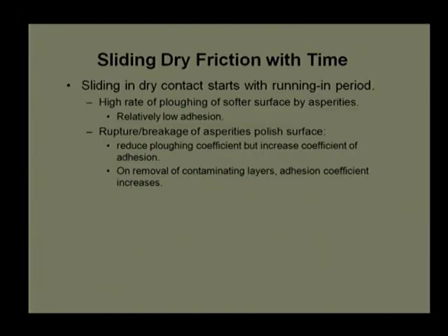And there is an observation which we got in the lab, that the coefficient of friction does not necessarily remain the same throughout, from the start of operation to the end of operation. Of course, we have already explained in the previous lecture what the kinetic coefficient of friction and the static coefficient of friction are. However, there is a slight change in the terminology. Many times in the Rabinowicz book you find steady coefficient of friction. Steady coefficient of friction is equal to the kinetic coefficient of friction.